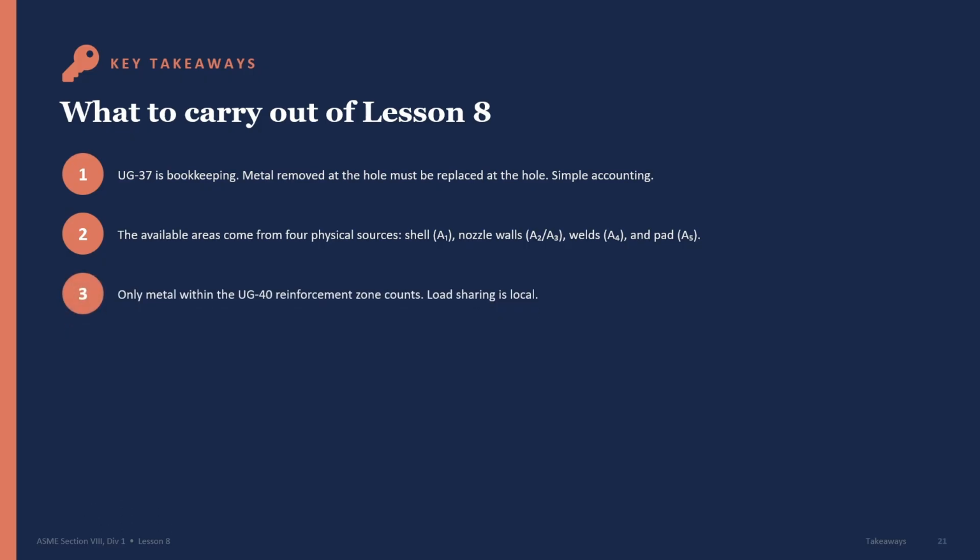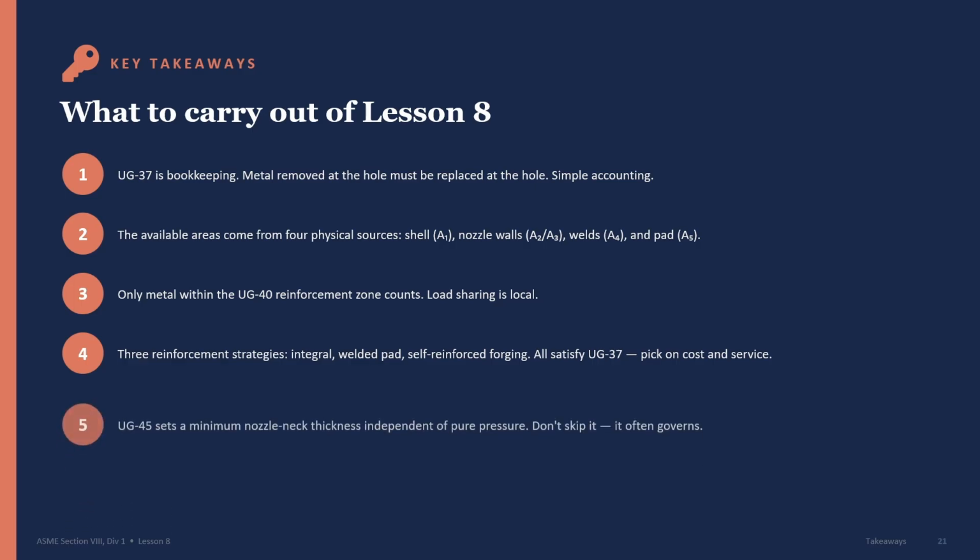3. Only metal within the UG-40 reinforcement zone counts. Load sharing is local. 4. 3 reinforcement strategies: integral, welded pad, self-reinforced forging. All satisfy UG-37. Pick based on cost and service.